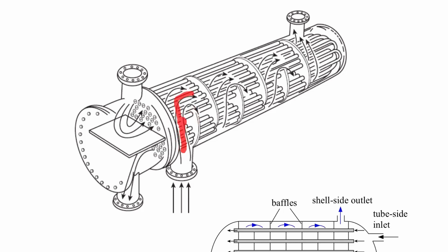So you go from a cross flow arrangement to then either parallel or counterflow, and then it switches back to crossflow and goes up and down and up and down all the way around the full system. So this becomes a really complicated heat transfer problem, but from a practical or construction standpoint, this is often done. If the point is just to get steam in these tubes to boil, which is happening pretty much at a constant temperature, you don't really care what the local temperature is. You just are trying to add heat from the salt.